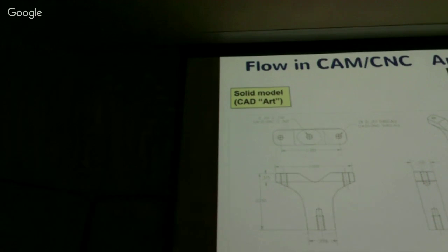So what we have in lab for our first lab is a set of steps by which you will learn to become a CNC operator. Now, I can train a CNC operator in 15 minutes. What you have to train them how to do is open the door. Usually there's already a part in there. You have to train them to take the part out, put the new part in, clamp the fixturing.